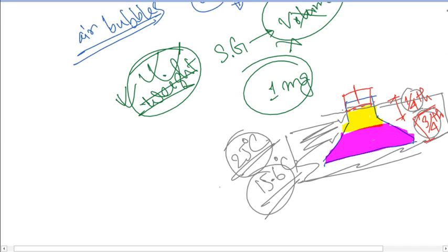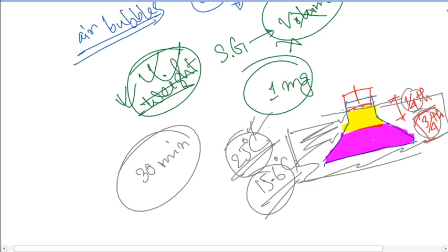So again you will keep it in the water bath for not less than 30 minutes, so that it reaches the test temperature. After that, the similar procedure applies: any extra volume of water will be expelled through the hole, and finally you give the stroke and dry all the surfaces, one stroke on the top of the surface and the required strokes with the towel on the outer surfaces after removing it from the water.